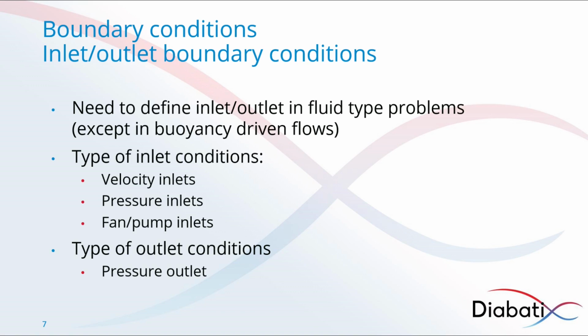And in this boundary condition, we specify a value normal to the boundary patch. We can either specify a velocity value, which you can do if your velocity at which the fluid enters the domain is known, or a mass or volumetric flow rate. And this is often used when the flow rate is a known parameter, or if you want to calculate, for example, the pressure drop throughout the system. So in the platform itself, you have several entries. You have the temperature, then you have U, m dot, or q dot, which are respectively a velocity, a mass flow rate, and a volumetric flow rate.